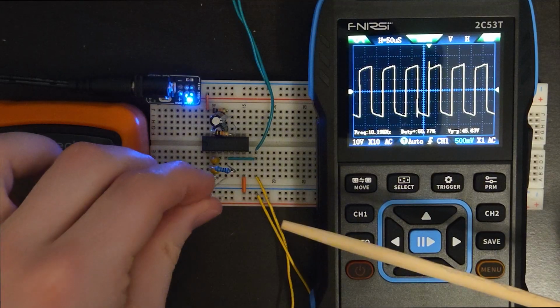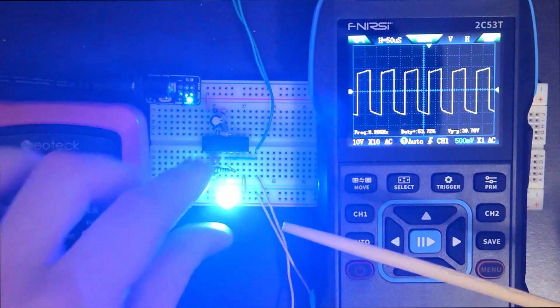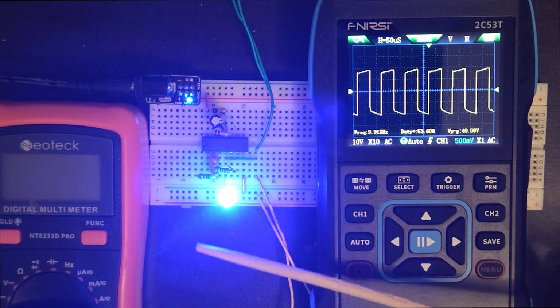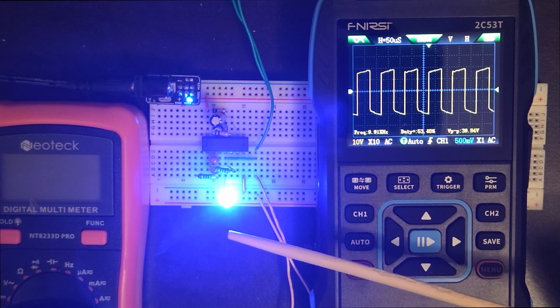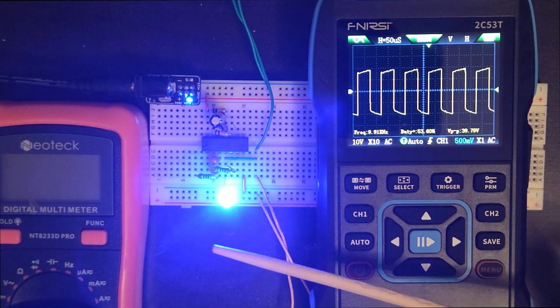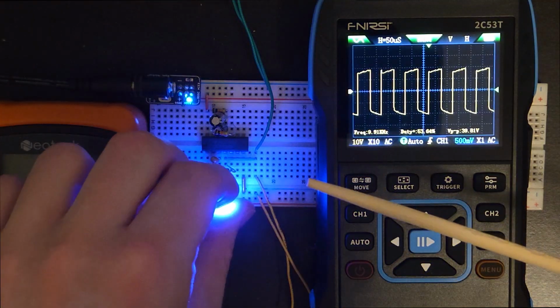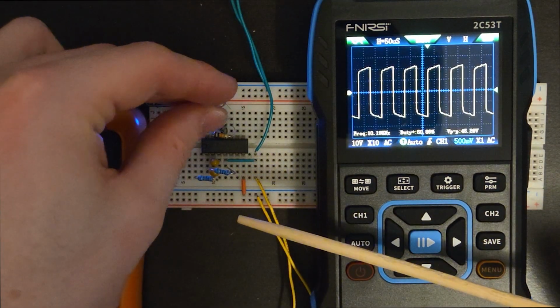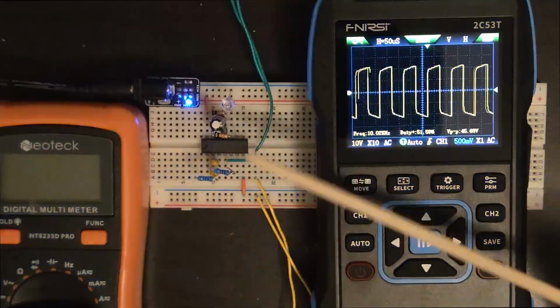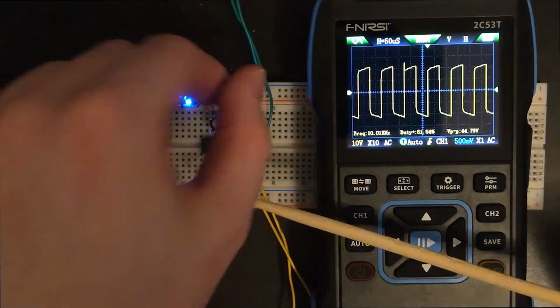So the easiest way to check a clock circuit, an astable multivibrator in this case, would be with an LED. We're going to see it constantly on because it's oscillating at 10,000 cycles per second, and so persistence of vision doesn't allow us to see it. But if we check this mirror circuit just with bigger resistor and capacitor values, you can see the oscillation right there.